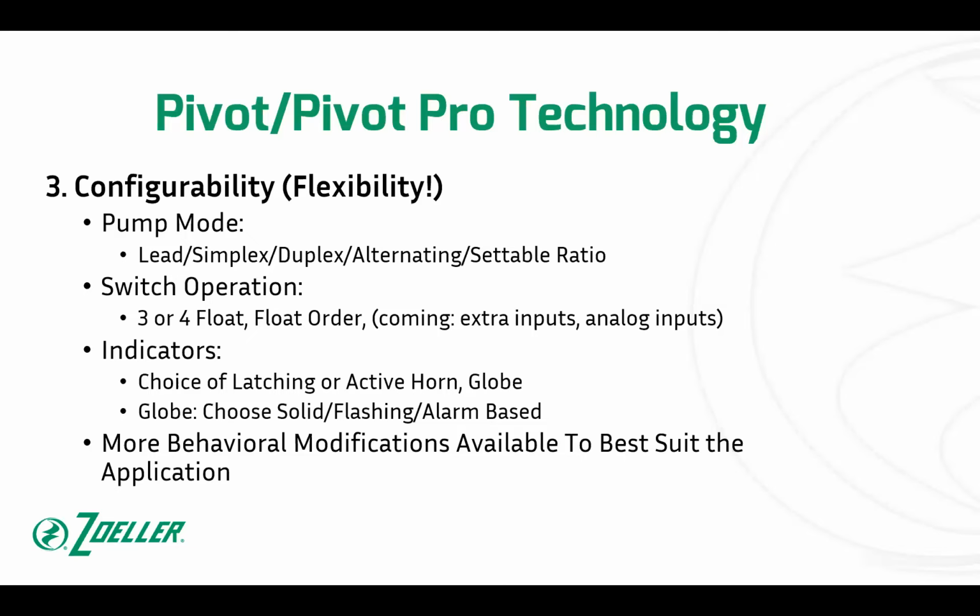I want one pump to wear out well in advance of the other one wearing out, because it may take me a week or 2 to get a pump changed or something, and the worst thing is having no pumps. So I want uneven wear. So what the lead mode allows you to do is to just select that 1-to-1 ratio to be whatever you want it to be. You can have it be 3-to-1, 10-to-1, 99-to-1.